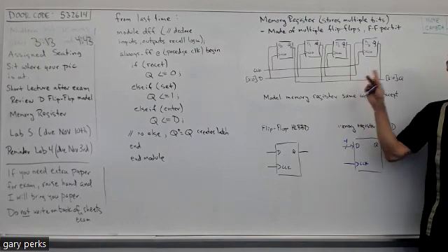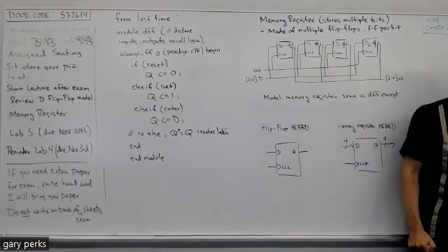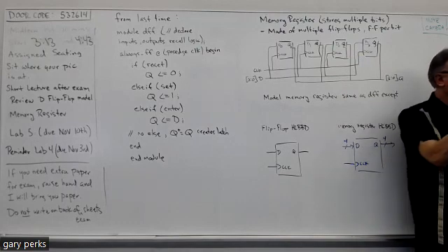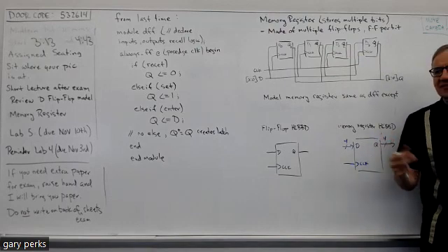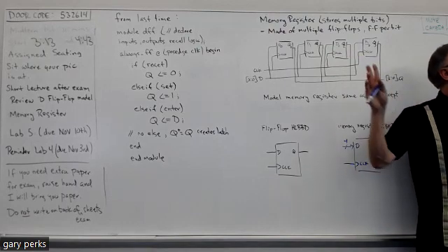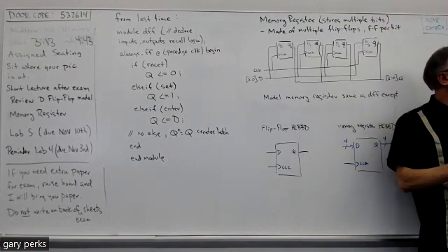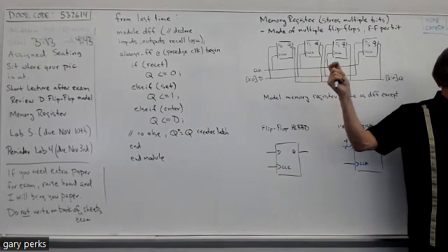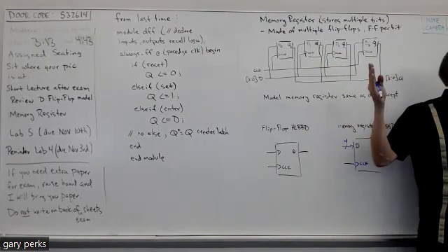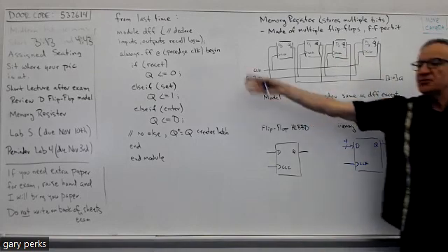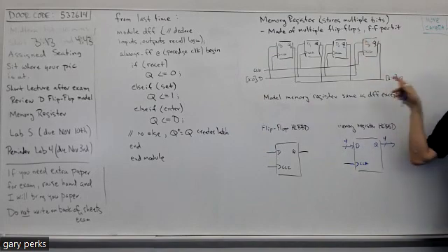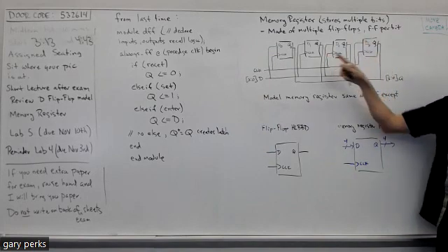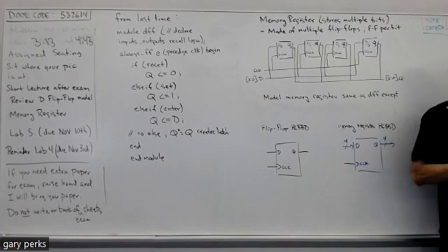But what did you have to do to connect all the adders together to make the RCA? You had your individual half adder, your individual full adder. But then what else did you need to model it? Well, the internal signals, yeah, because you had to connect everything together in the structural model. Remember, there was a whole other design source that connected all the lower levels together. Well, you could do the same thing here, right? After you model your single D flip-flop, you could have a top module that makes all these connections. You could do it that way.